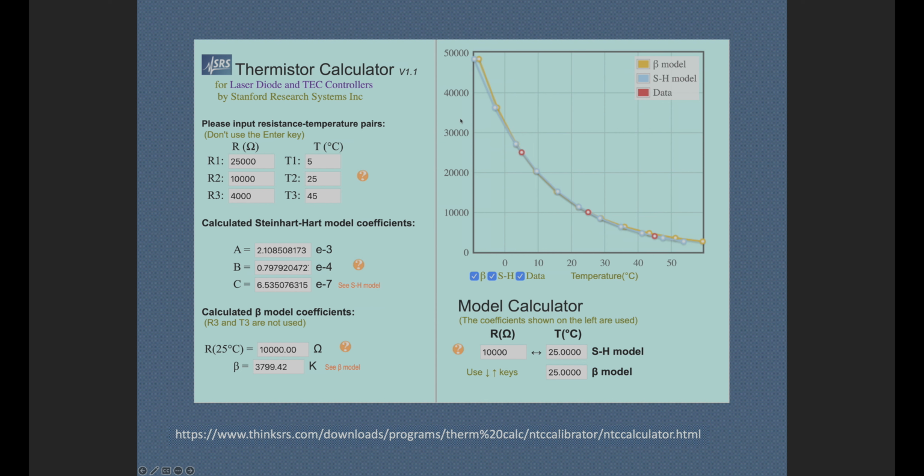As we continue moving up in temperature, we're down at 0 C. Looking at our Honda coolant temperature resistance on that sensor, and our epoxy thermistor. Okay, 30 K at 0 or roundabouts. Let's take a look at plus 1. Okay, and we'll continue on.